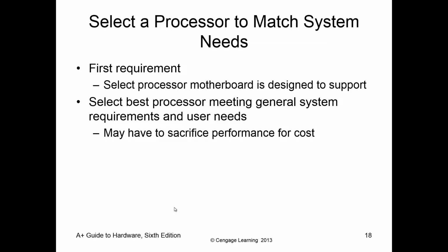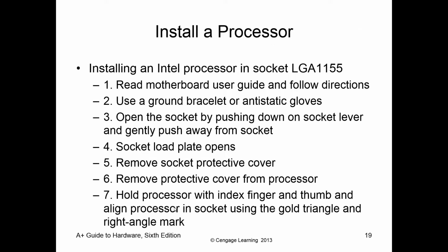Okay, so now let's talk about the installation process. First step, read the manual. Make sure you read the manual for the motherboard, read the manual for the processor, make sure you have everything ready to go, and you're going to be following directions. Next, ground bracelet. That also means take off your jewelry, prep for dealing with sensitive components. Protecting the component and yourself from ESD is extremely important.